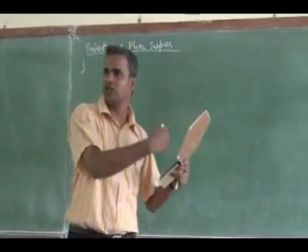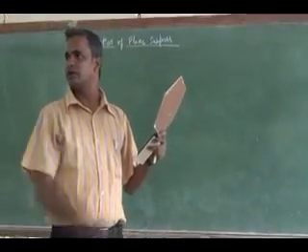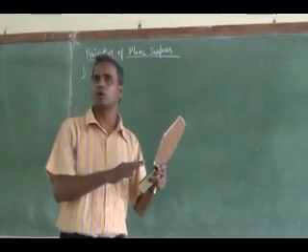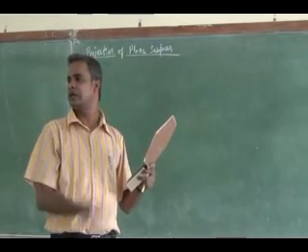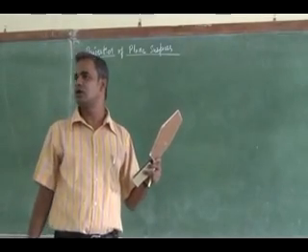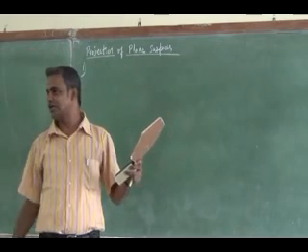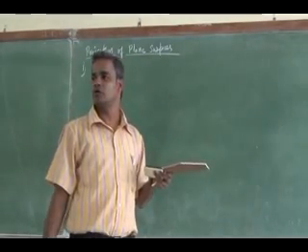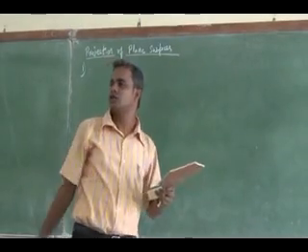So this orientation, that is, the plane is inclined to HP and perpendicular to VP. The surface of the plane is inclined to the horizontal plane. In this orientation, I cannot attain the true shape in any plane, whether vertical, horizontal, or auxiliary. So to draw the projections for this orientation, we have to draw it in two steps. First, wherever it is inclined, we make it parallel to that plane, so I can see the true shape and a front view. That front view will be a straight line.